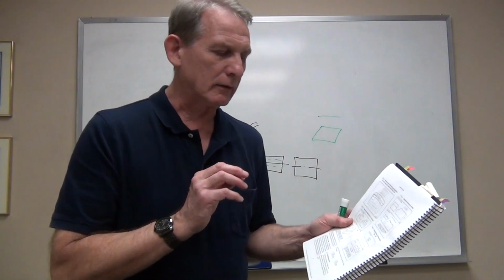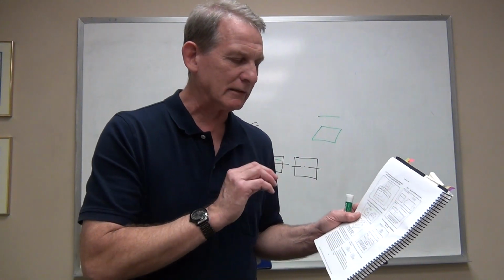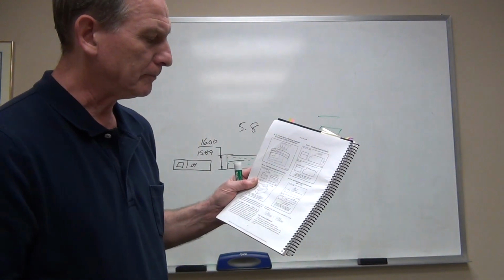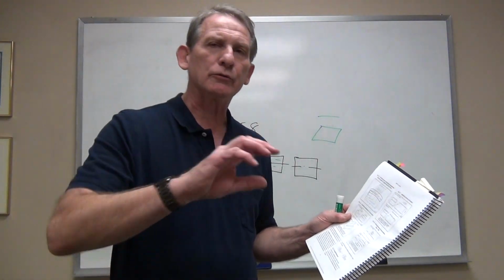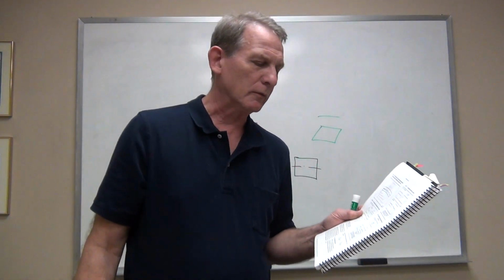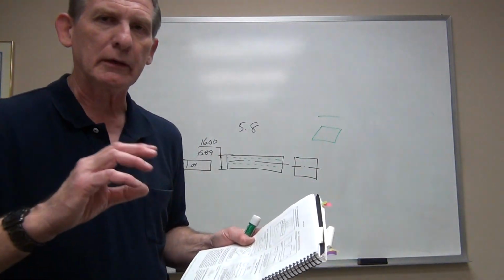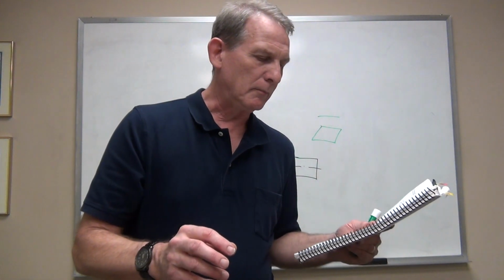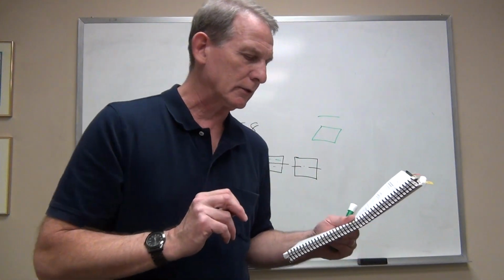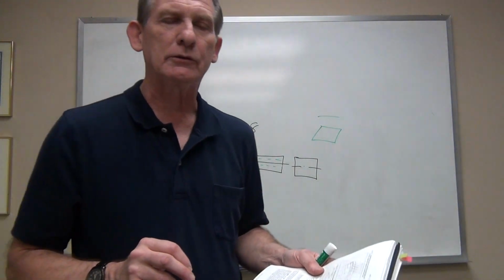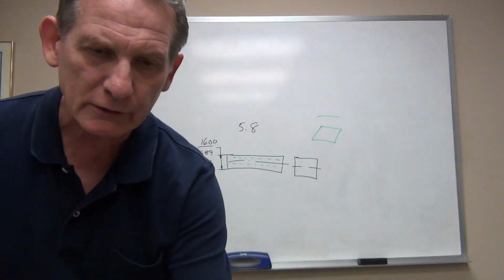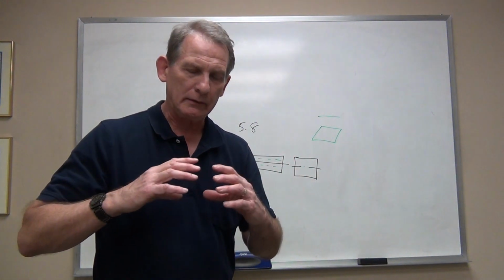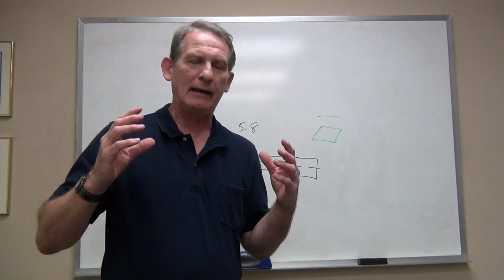The important thing to carry away from this illustration is that if you look at the boundary on the outer surface of the part, it would appear that that boundary is 16 and 40 thousandths. And the size tolerance is 16. So it looks like you've actually violated the size by giving yourself that tolerance zone for flatness. And that's not really the case.